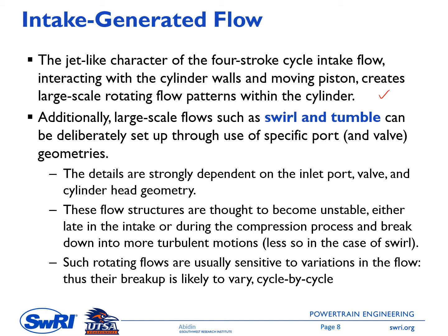And then this flow structure is thought to become unstable. So some of this organized flow will break into turbulence during the later intake stroke and also during the compression process. And some of this will be dissipated at the wall, okay? And all of this will be converted into thermal energy. However, the thermal energy is pretty small. It means that we won't be able to see the temperature increase due to this turbulent energy conversion.